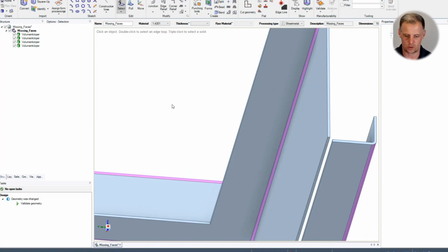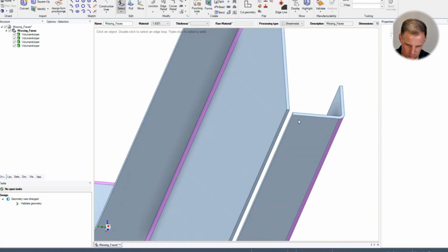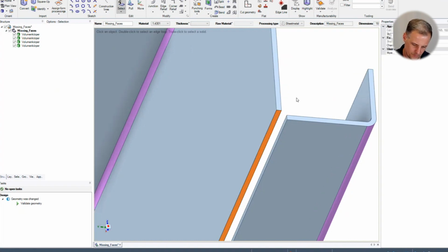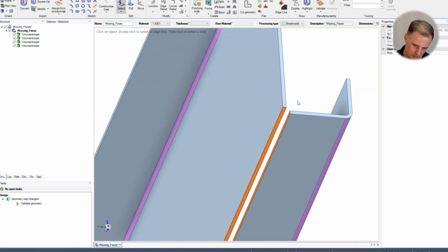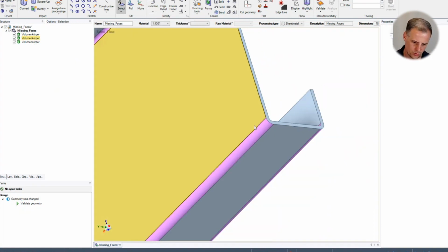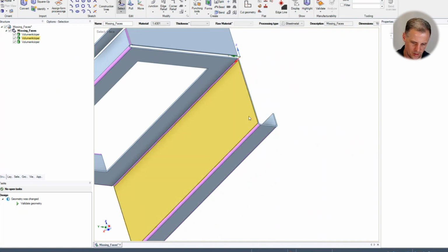Use the select tool, and with the control key, I can select more than only one face. And once these 2 faces are selected, I can use again the junction feature with active bend, and this leads to it creating a bend between these 2 faces.